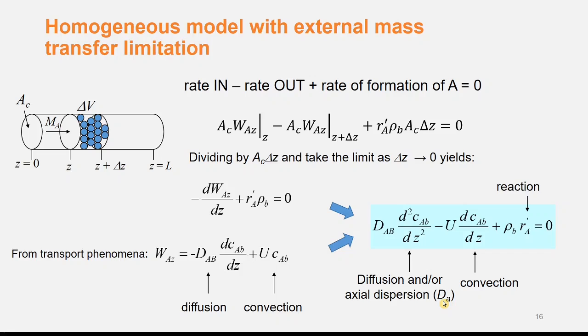Do you still remember the difference between diffusion, dispersion, and convection? Diffusion is due to the motion of the individual molecules in the fluid. It is typically slow. Dispersion is the relative motion of different fluid elements due to turbulence or due to velocity gradients. You may remember the term eddy diffusivity in relation to turbulence. It is the rate at which small elements of the fluid, which move in a random way because of the turbulence, mix with each other.